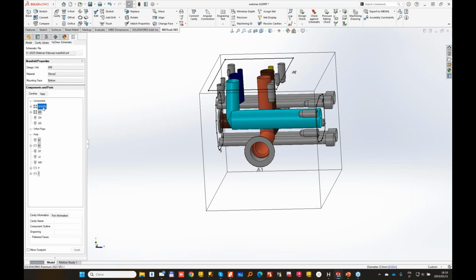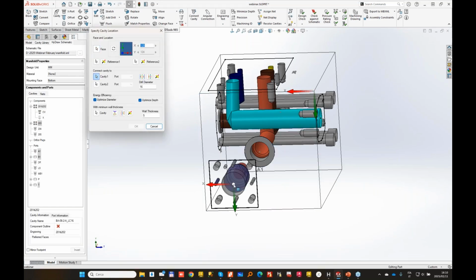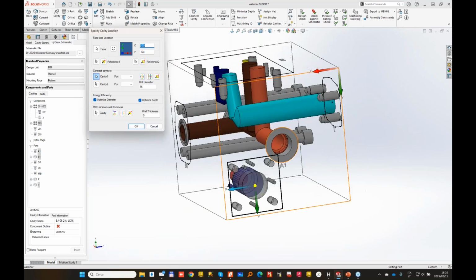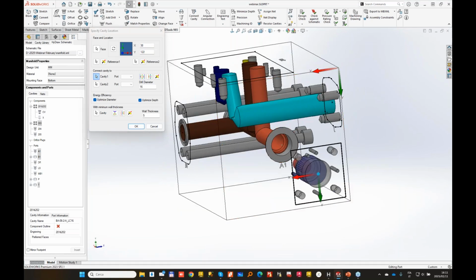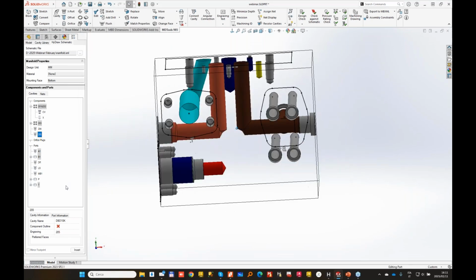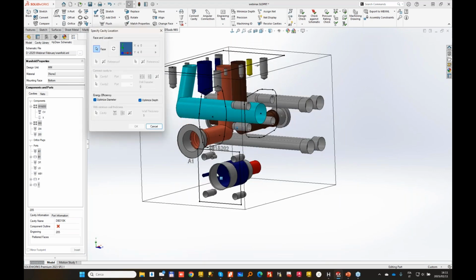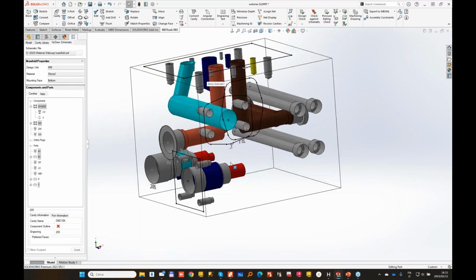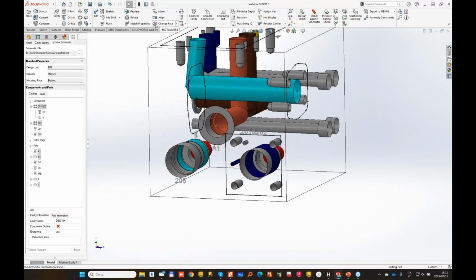Let me go and place the DIN pocket, which I want to position somewhere here. Well, maybe I move to a different location on this face. We also have a relief valve in the schematic, a DBD10 Bosch Rexroth. So let me insert it and let me place it somewhere here. That may not be a perfect position. I need to connect the blue lines. So let me swap cavities.